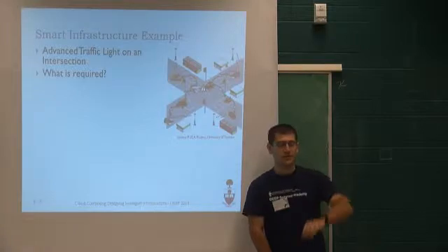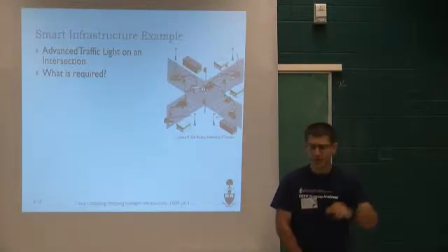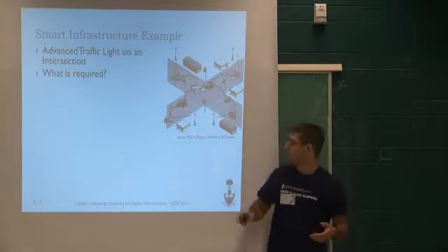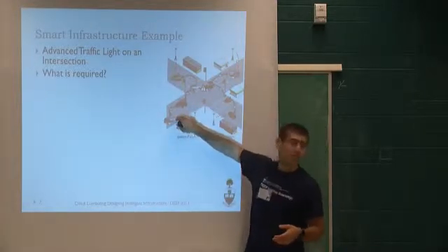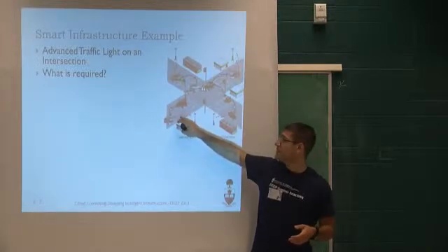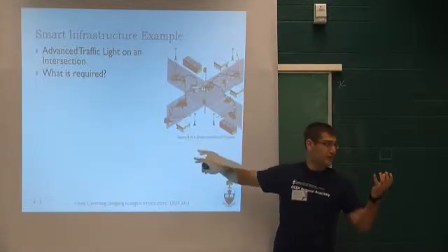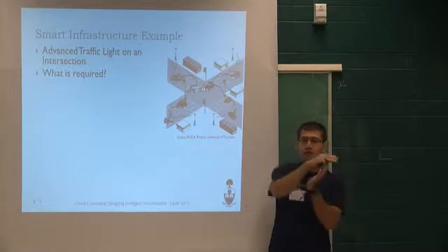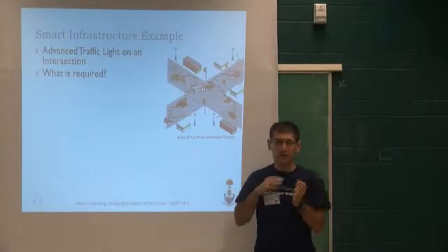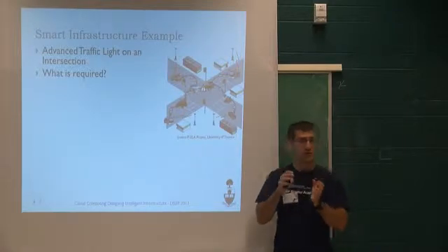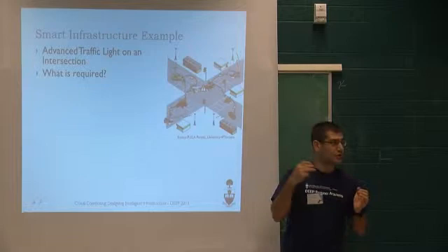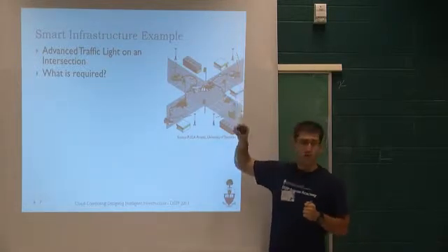So you start with what Kartik is mentioning, which is based on the volume. So you'll be measuring. You have devices in the pavement that are inductors that detect when a vehicle goes through. Those are called loop detectors. We're going to discuss them in detail tomorrow. That's how you can measure how many vehicles are going through on the different approaches.